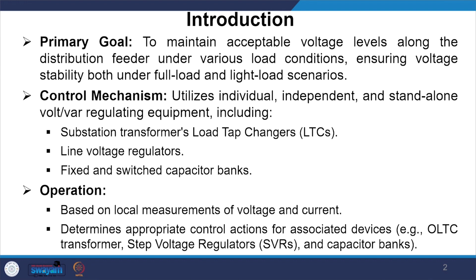Imagine we have the source, maybe substation, bus 1, bus 2, bus 3, and we have different loads connected at different buses. Now we are very clear, due to the basic fundamentals of physics, having resistance in the conductors, the voltage experienced in different buses, as you go away from the substation, will be low. Now the target is how to make sure that the voltage drop is not very significant so that the equipments connected to my different zones or areas or the buses are not going to get damaged.